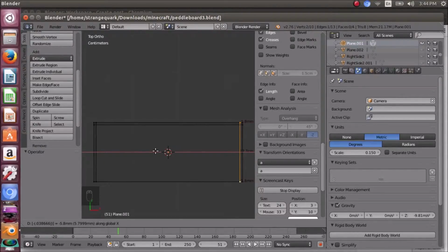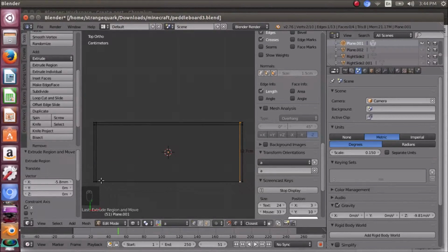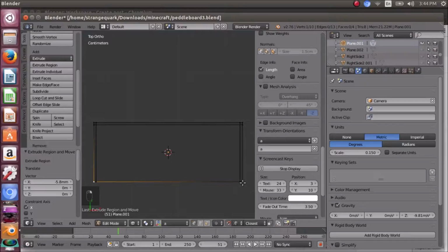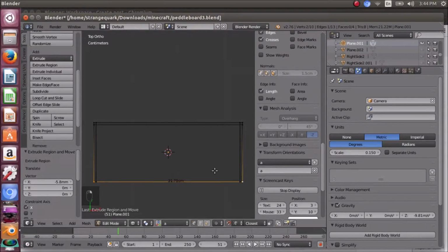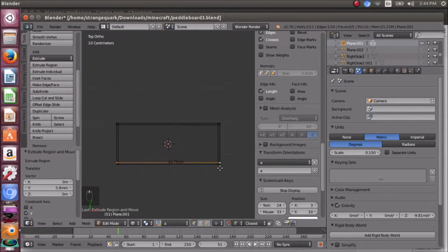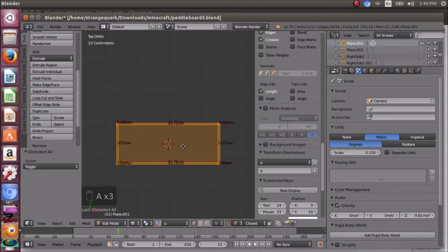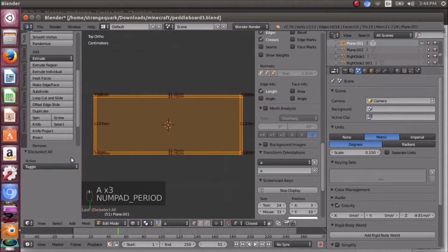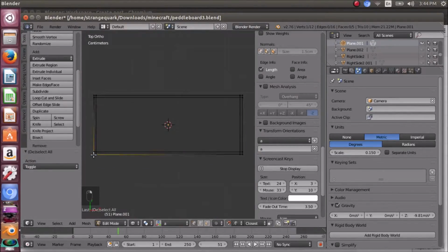And then we'll select two more vertices, and that'll complete the extrusions that we need for the plywood wall thickness here, 0.038666. So we now have a completed extrusion for the walls.